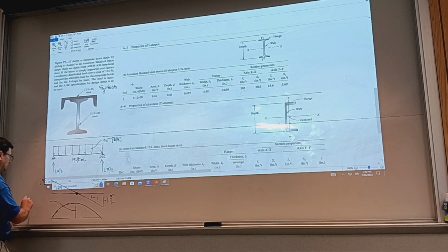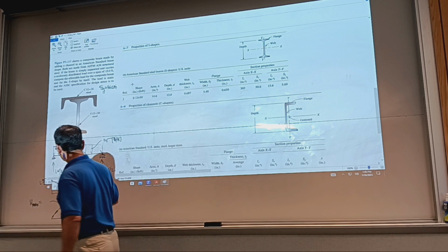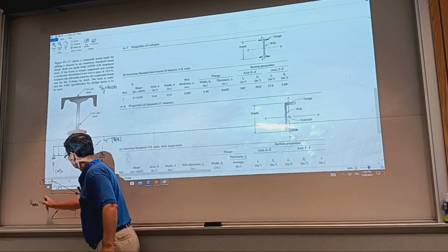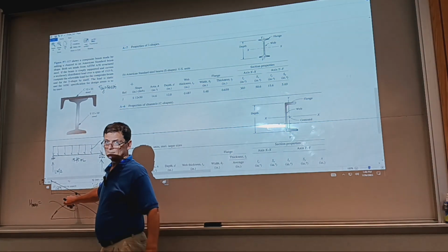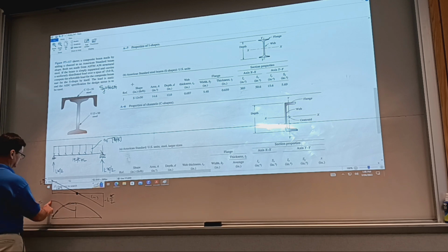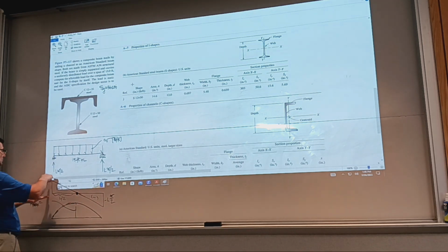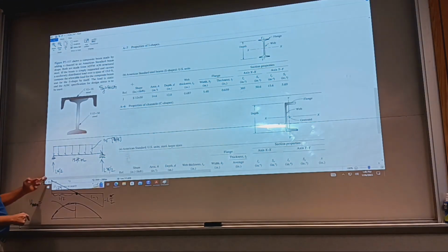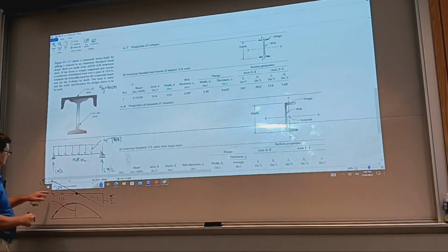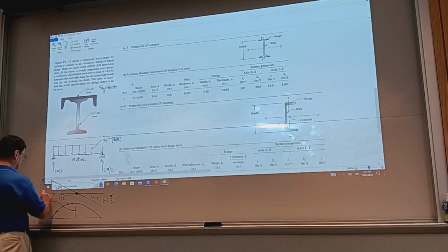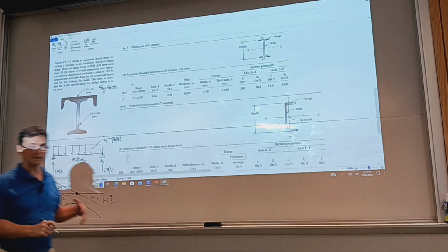How big is this maximum moment? It starts with no moment, so it's the area of this triangle. This is L over 2, likewise the other one. So it's half of L over 2 times L times w over 2, so Lw over 2, 4, 8: L times w over 8. This is the maximum moment that will occur.